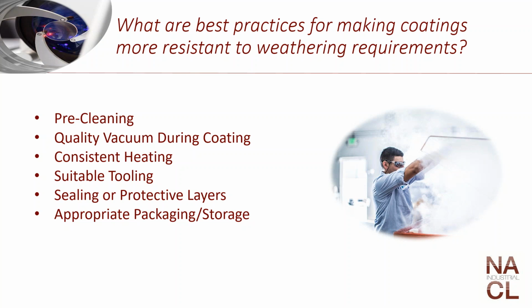Same with plastics. Tooling can become very important here. Suitable tooling will allow you to accurately coat your optic and not have any weak spots in your film. Normally, when you'll see a film fail, it fails at the edges of the part. And almost always, when the edge failure occurs, it's right by where the part was optically held. So if you're holding the optic too tight, or if the tool itself wasn't perfectly cleaned, you can create an issue just by your tooling. So suitable tooling that's appropriately cleaned and appropriately sized for your optic is very important.